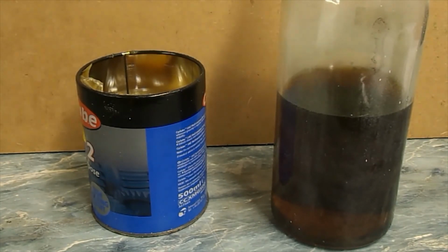Lubrication. Choice of lubricant is an essential factor in ensuring the proper functioning and long service life of bearings. Lubricant does the following things. It facilitates movement, it avoids wear and premature fatigue, reduces internal friction, ensures that the bearings are sealed against external bodies, reduces the operating noise, and protects the bearing against corrosion.